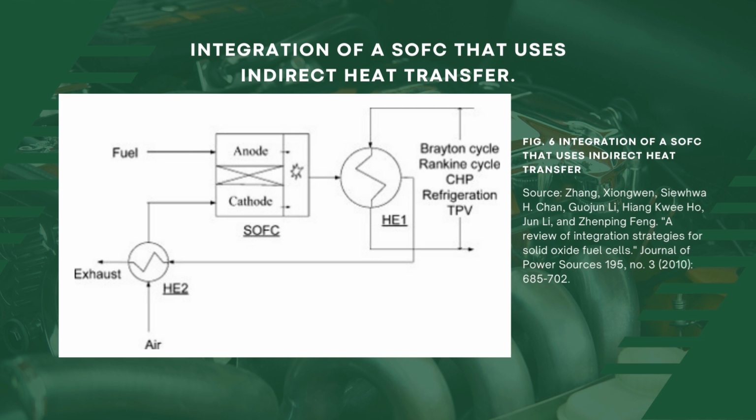Aside from the SOFC cycle, the other closed cycle may be a thermal power generation plant, that is the Rankine or Brayton cycle, or a TPV, that is thermophotovoltaic, or a thermal utilizing module, such as a combination of a CHP system with a refrigeration cycle. So, any type of power generating cycle we can include here.